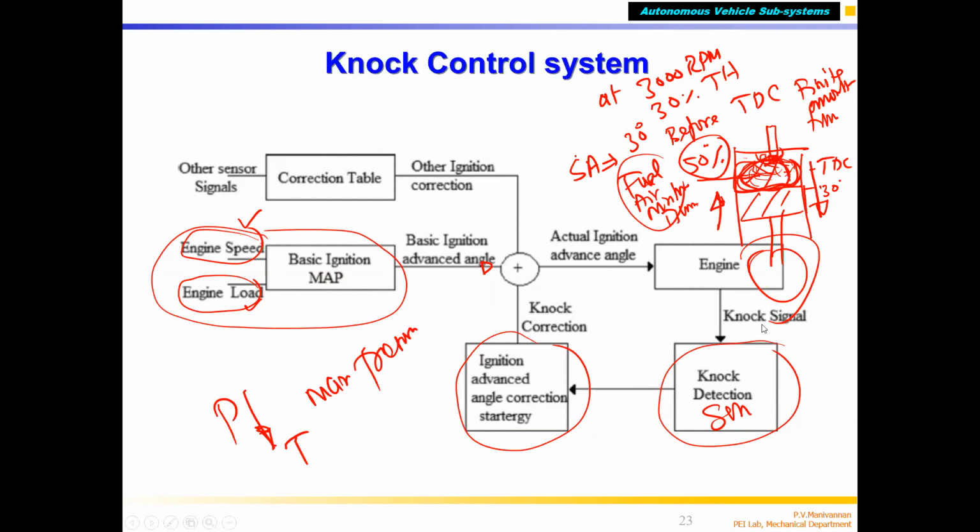So the thumb rule, the thermodynamics rule, says that if the piston comes to TDC during the compression stroke, by the time the piston reaches TDC, at least 50% of the air-fuel mixture should be burned, not more than that and not less than that. To do that, you have to give the spark in time. Why? The 50% fuel-air mixture has to burn. It takes a finite combustion time. Combustion cannot happen in 0 time. In the universe, nothing can happen in 0 time.